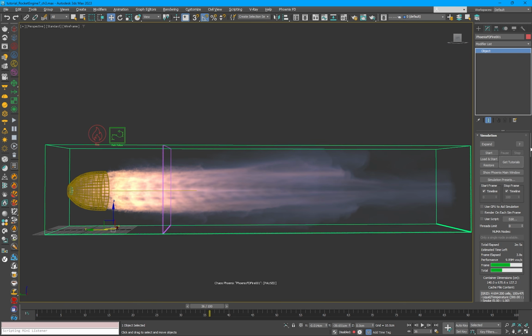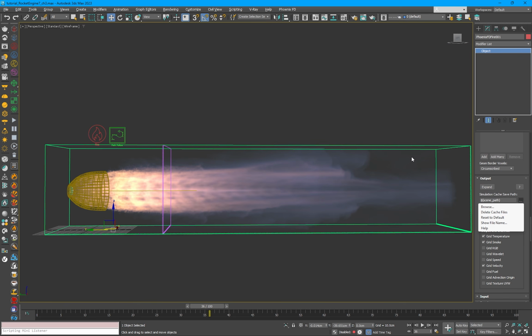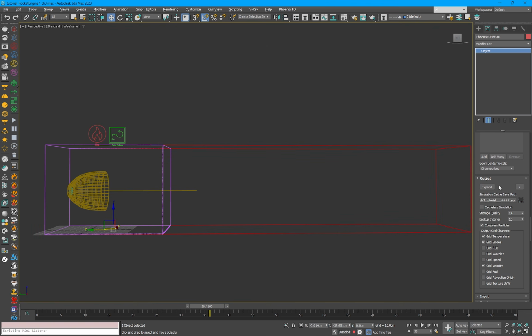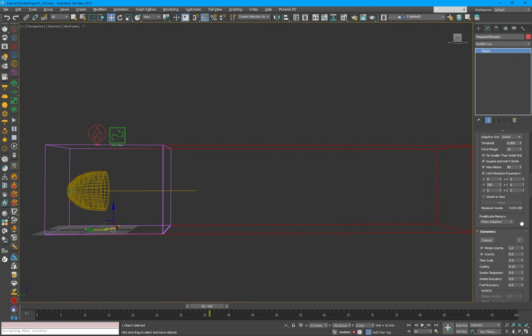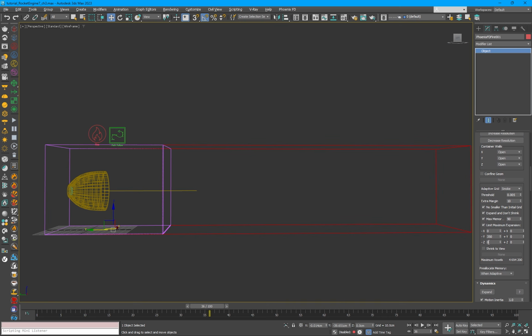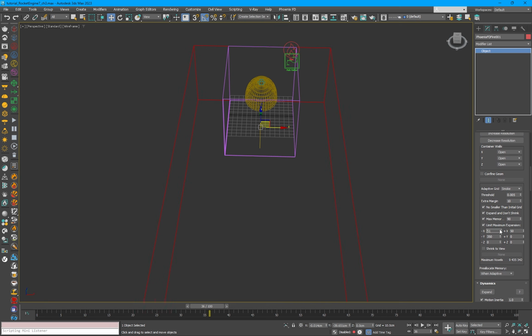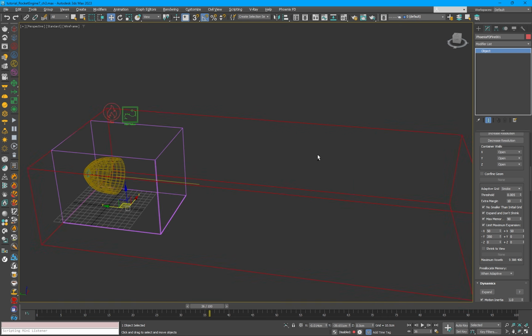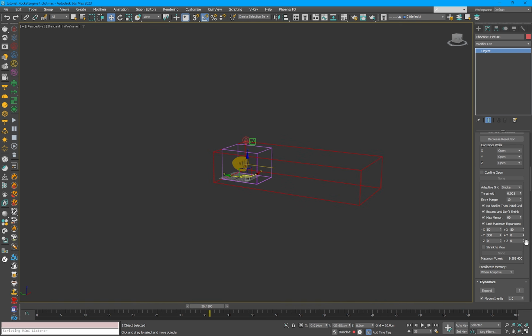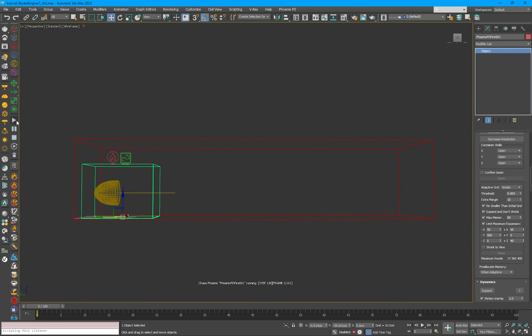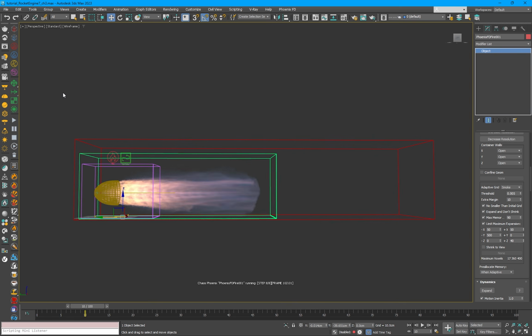Alright, our next step will be to make output for our cache, because before we were working in cashless mode. And let's give some more room for our simulation from the sides, like 50 additional points. The height 40, and the length of our simulation box significantly bigger. And let's run our simulation.